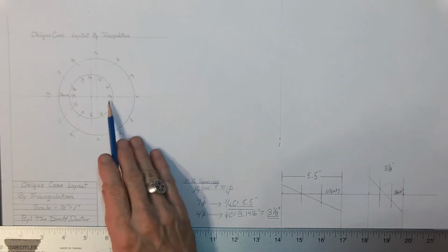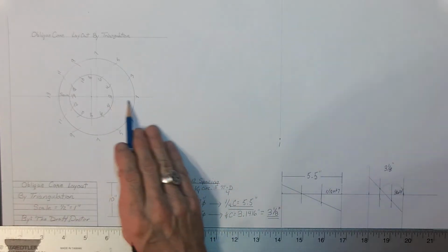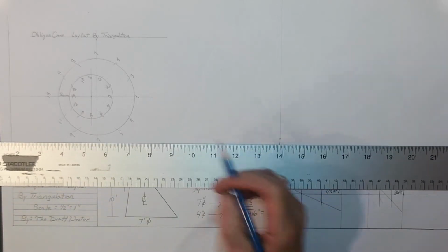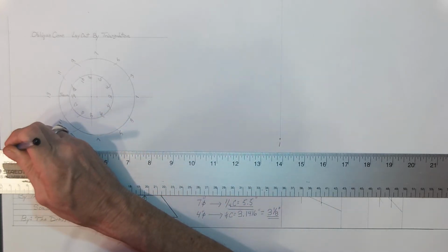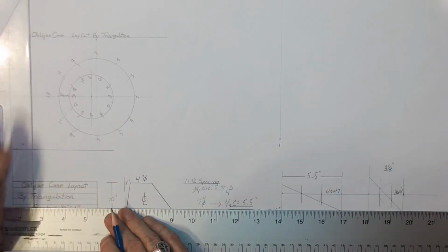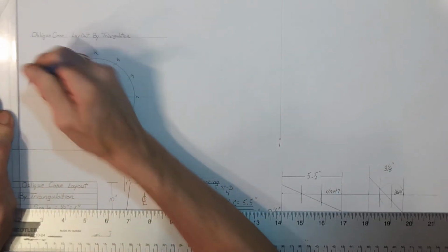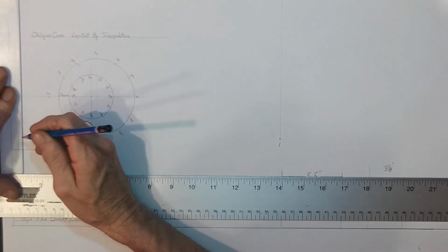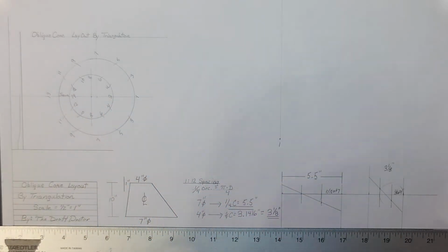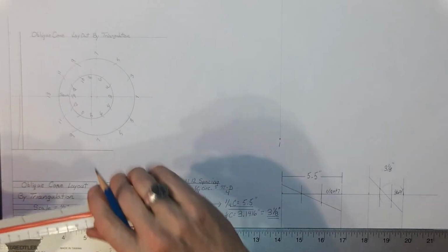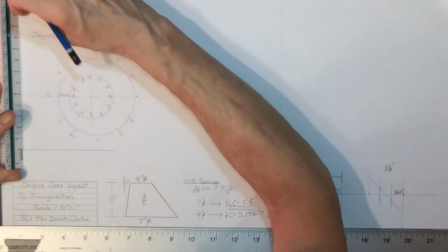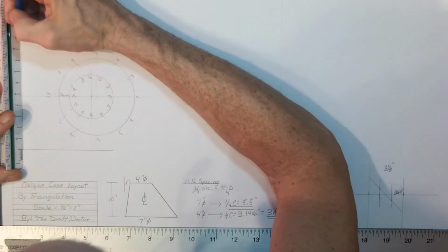In order to find my point 2, I need to triangulate this fall from 1 to 2 over a 10-inch height. So what I need is a true length triangle. Simply, I need to build a 90-degree grid, which I have right here. Oops, that slipped. Come in a little bit now. And what I'll do is measure my 10 inches in height on my 1/2 inch scale. So from 0, this now will represent the height of my fitting right here.